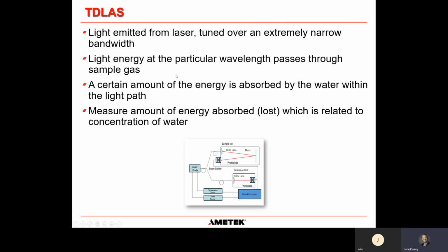But quartz crystal microbalance, or QCM, is one of the only technologies that has this built-in inherent capability to it. And then last, just talked about the newest entrant, which is TDLAS, or tunable diode laser absorption spectroscopy. In this case, there's a laser diode that's tuned to a specific wavelength, and the wavelength it's tuned to is the wavelength where water molecules will absorb that light energy. So the laser diode emits a laser beam, and the laser beam travels into a sample cell, which is where the process gas is flowing.